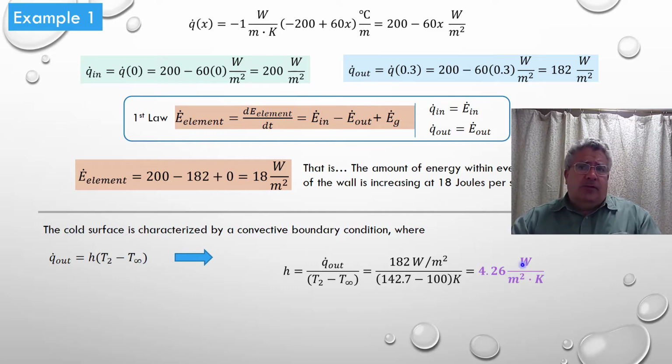All right, so that gives us a quick overview of how Fourier's law is used to allow us to create the heat equation, which is second order in space and first order in time. And we've looked at applying boundary conditions. Since it's second order in space, we need 2 boundary conditions. And we've looked at least one example of the steady state case.